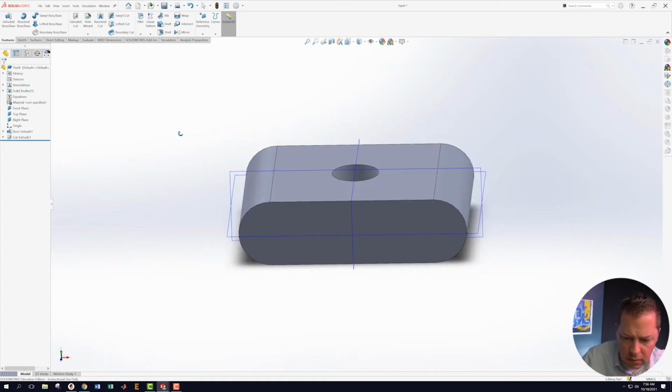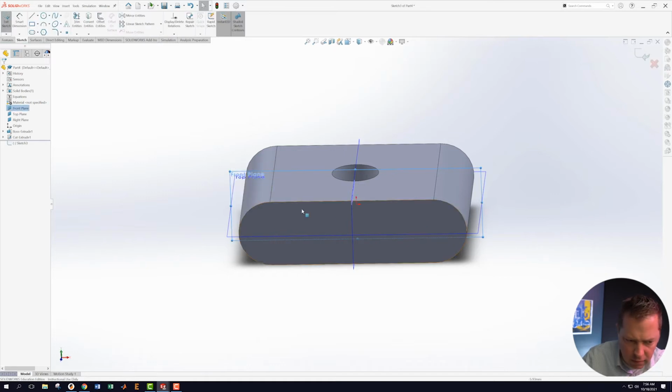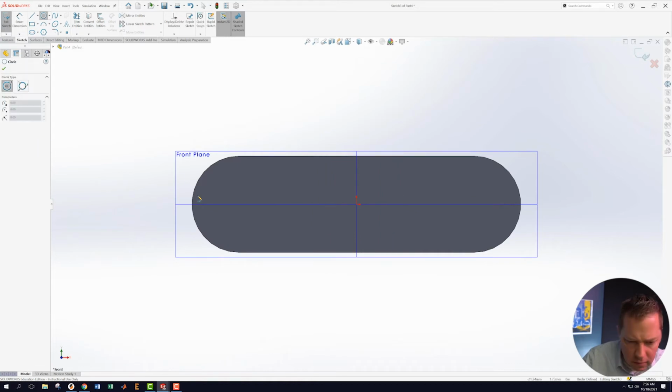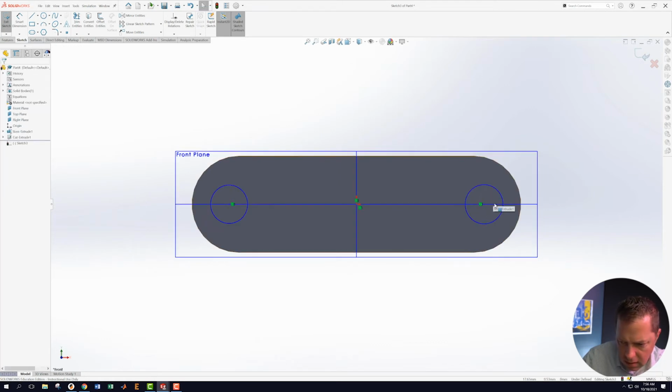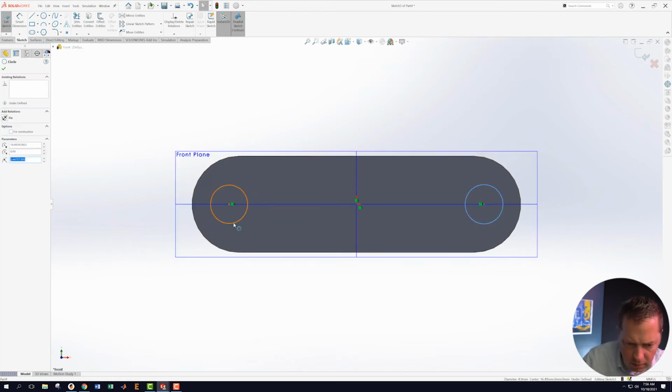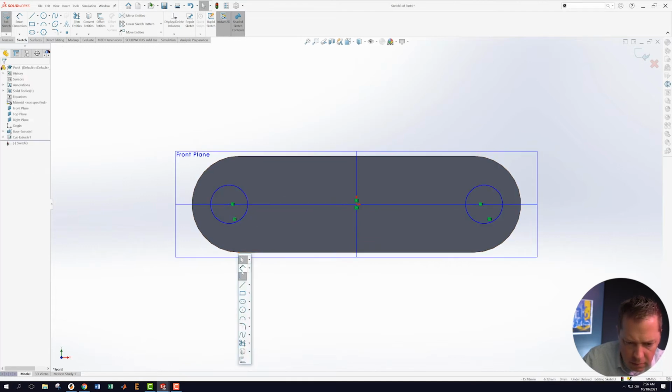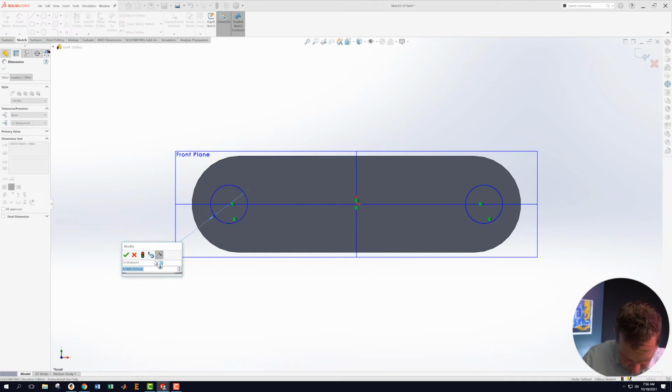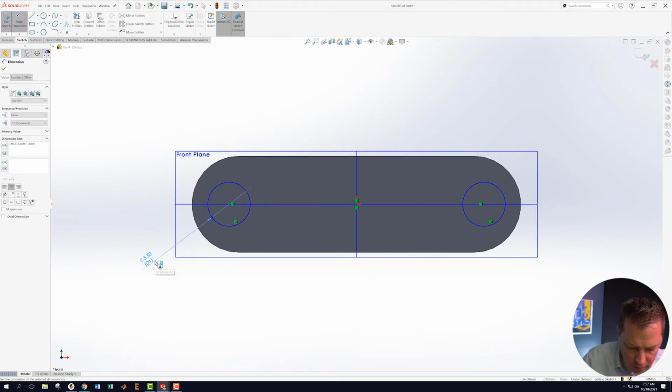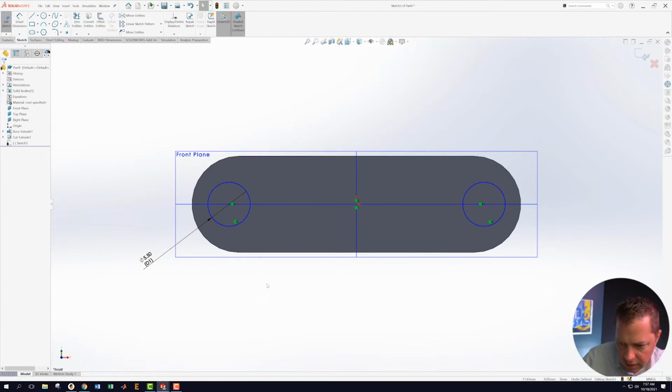Now let's get these two small holes, the two holes on these front faces. Okay, those are on that line, on that line. This one and this one are identical to each other in terms of size. Let's actually put a size on that. What is that size? It is 5.5, which is the same diameter as that long shaft.